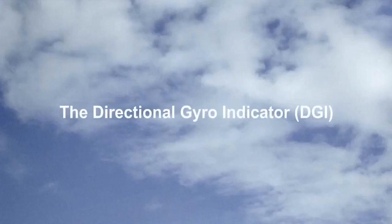In this lesson, we are going to define the purpose of the Directional Gyro Indicator, or DGI, and look at its construction and principle of operation. The DGI is sometimes referred to as the Direction Indicator, or DI. We will also look at the errors which the DGI is subject to and how the effect of the errors is reduced.